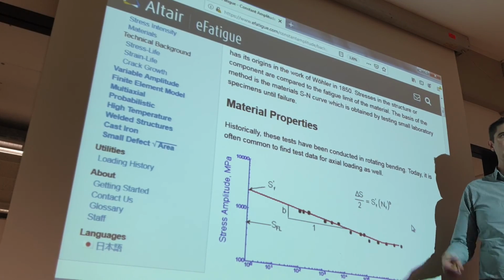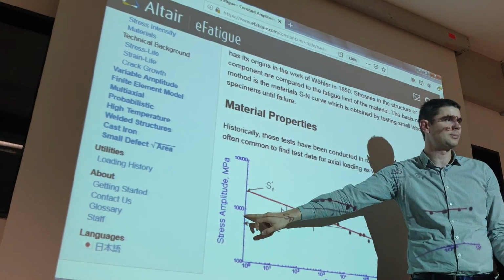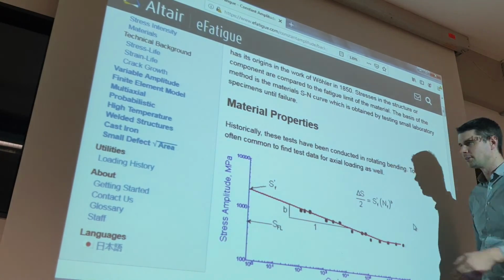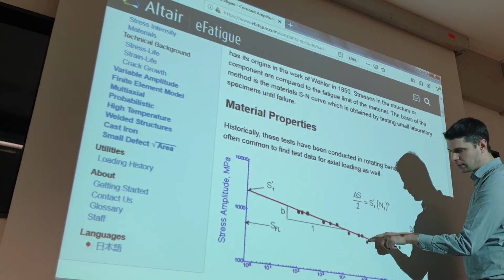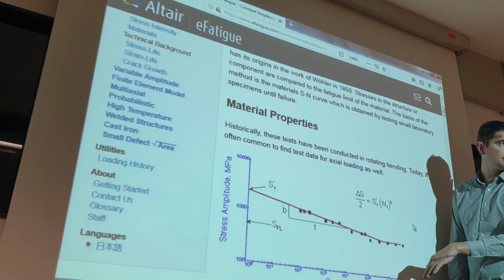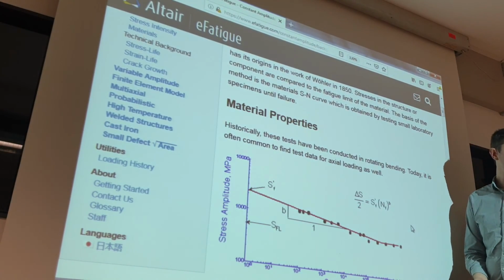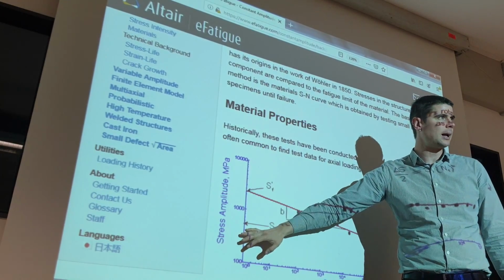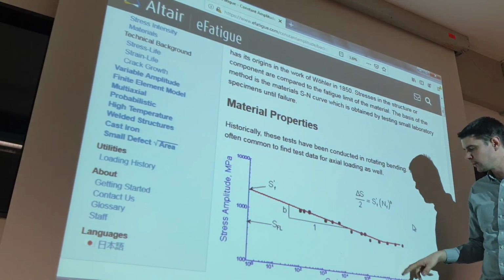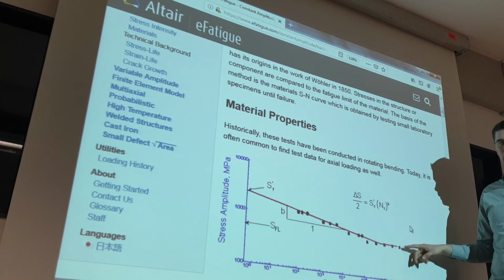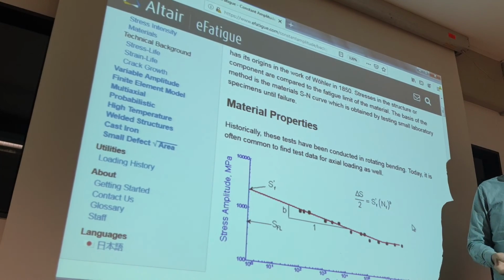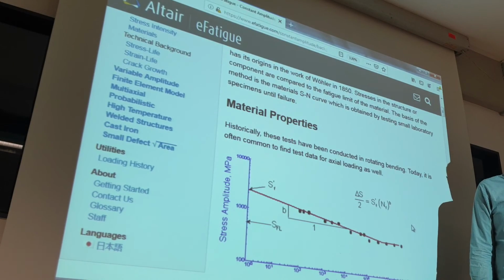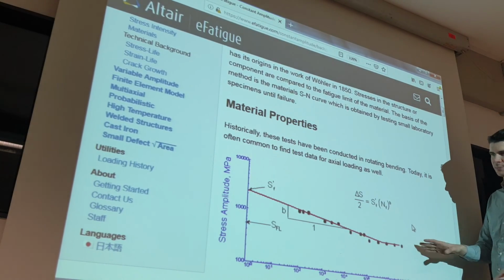Then I take the next part and apply, for example, 900 megapascal, load 0, 900, 0, 900, and now after, for example, 100,000 loads it is broken. Yes? So then I take one part and apply, for example, 500 megapascal, and I did it 10 million times, and it's not broken. Yes, and then I say, okay, more than 10 million times I cannot do. It's not possible. It means this is my limit.